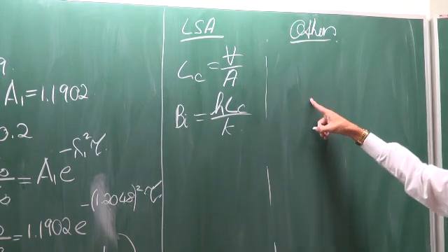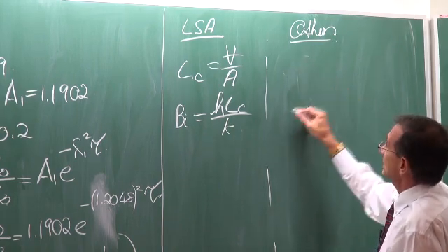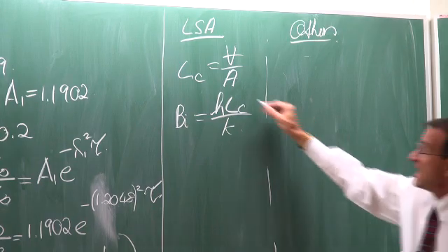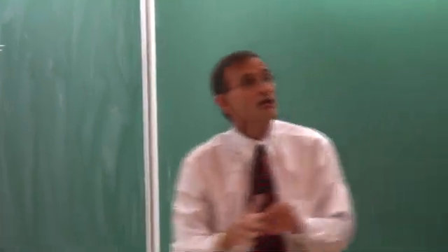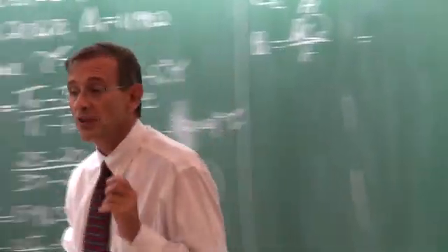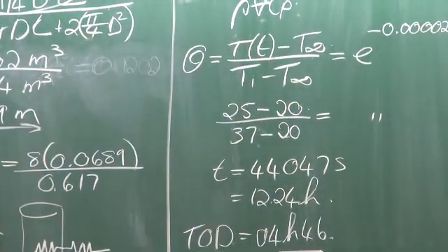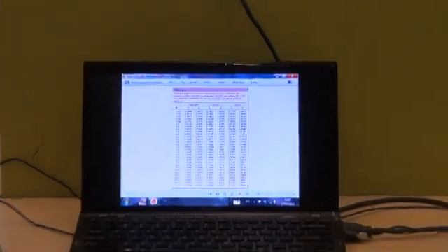But for the others, when you calculate the characteristic length, it doesn't have it. And the Biot number is not based on the characteristic length. You have to go and check in the derivation what was used with the calculation of the Biot number. And that's the fine print that you have to be careful for. And that fine print is actually everywhere. You must just know about it.